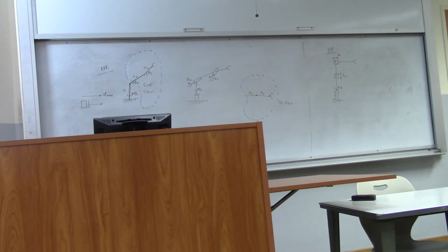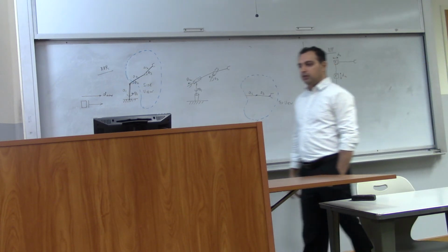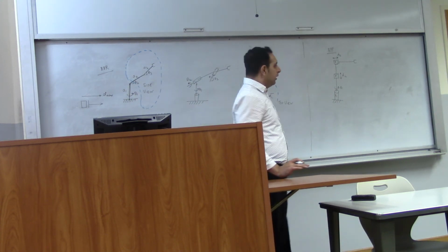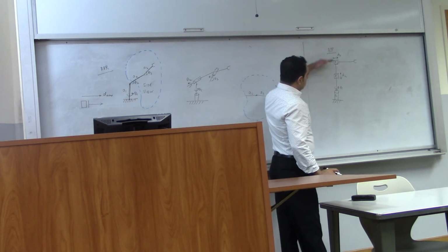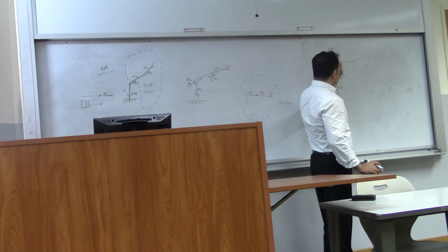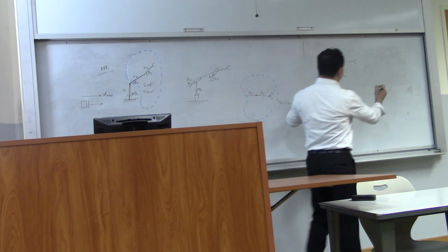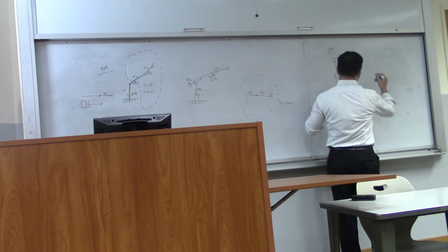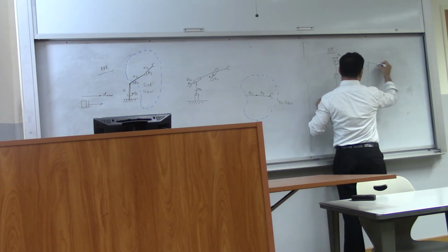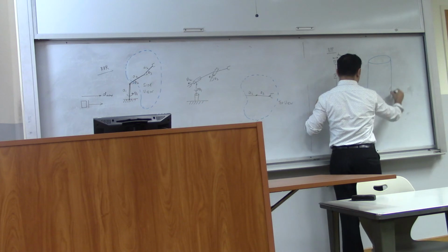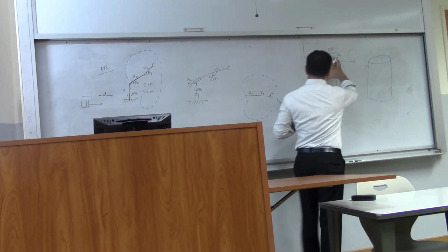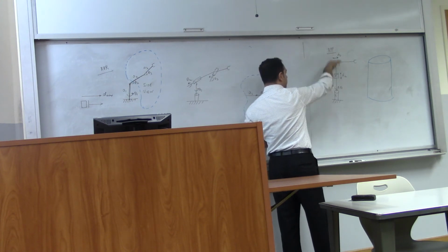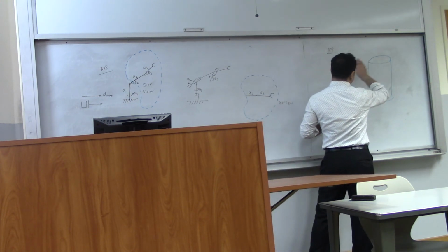Only around the axis. It will be round. Okay. What else? It's a cylinder. Cylinder. Yes. So this will be up and down, and this will go forward and backward. If you look from the side, the view will be just like this. The side view for this manipulator will be like this. Because this is going to trace a circle. When this rotates, it will trace a circle, and it can go up and down like this, D2, and this will take it forward and backward.